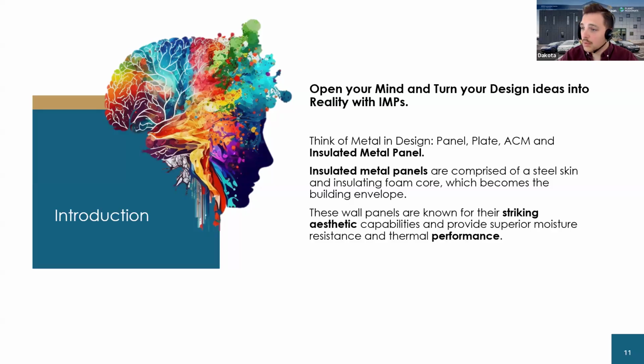They really do a good job of supporting your design intent no matter which category you fall on that spectrum. They can deliver performance, high efficiency wall systems, even behind a system that's not an exposed metal building. But alternatively, they can also be the face of the building, offering exceptional performance while effectively communicating your design intent through exposed metal facade systems. So think of the aesthetics of a similar extruded panel plank system, like aluminum composite material, ACM. These looks can be achieved by IMPs as well.